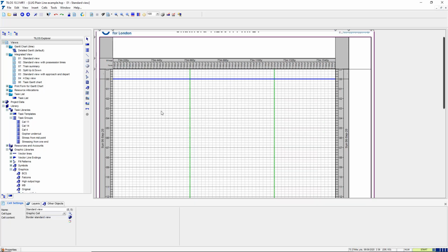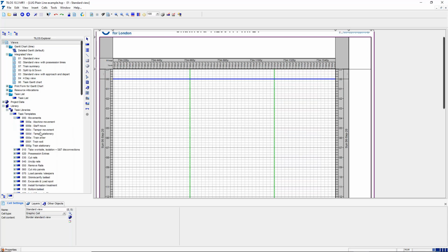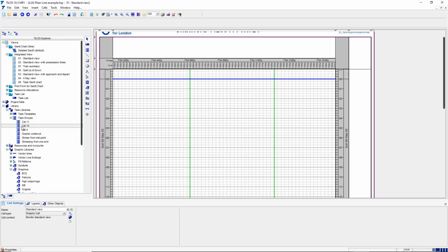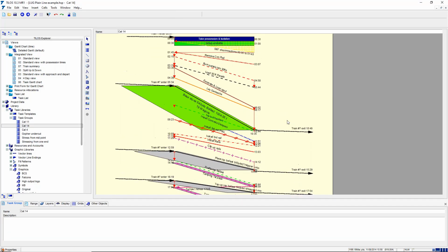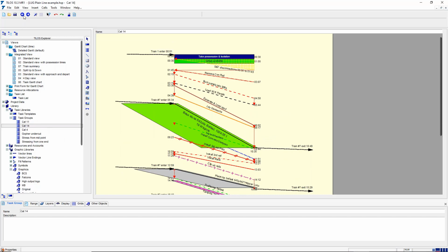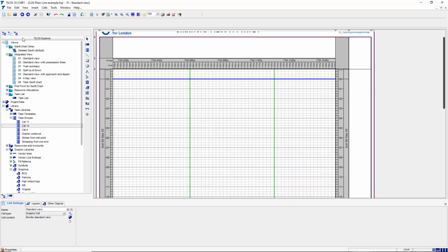So we're going to do a small amount of work overnight or over a weekend, and rather than taking individual tasks and building individual stages and linking them together, we typically do things in standard ways, and these standard ways are pre-planned as a fragment of a project, a fragnet, where we've got all of the tasks and we've linked them together in advance.